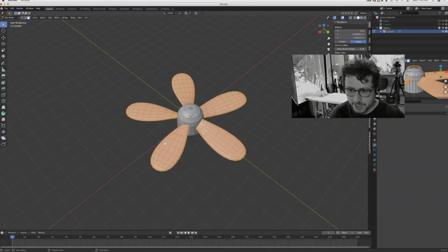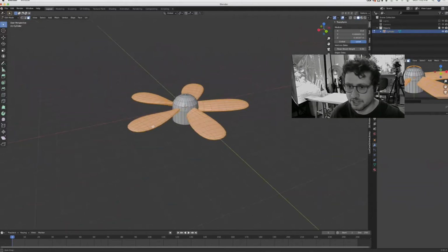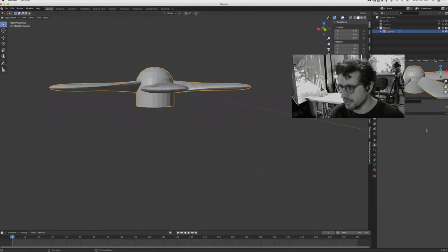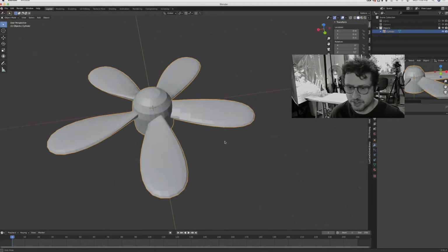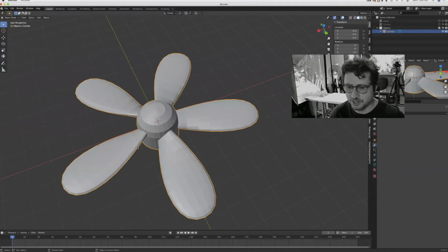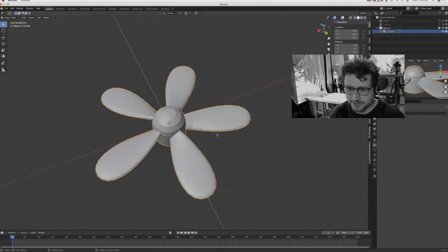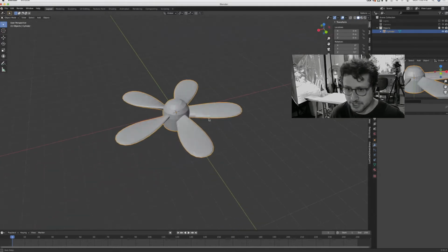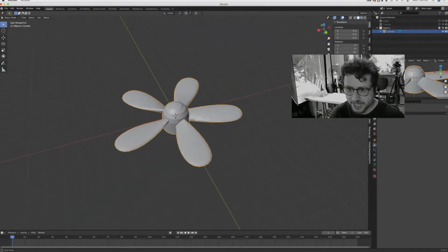And now you can see when I look here, we just have one mesh for this whole piece. And you can also see there are no modifiers on it. So when you do an auto Boolean function, in addition to merging or subtracting or whatever, it's going to apply all your modifiers in the process, which in this case, we want that.